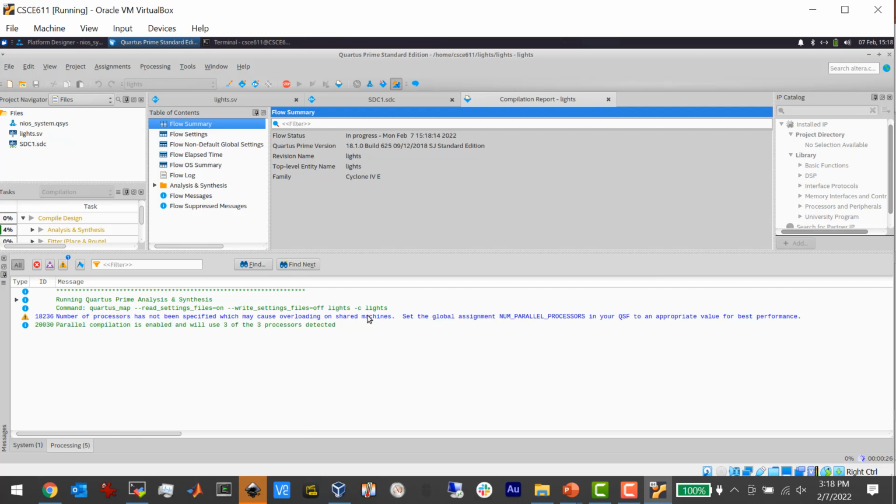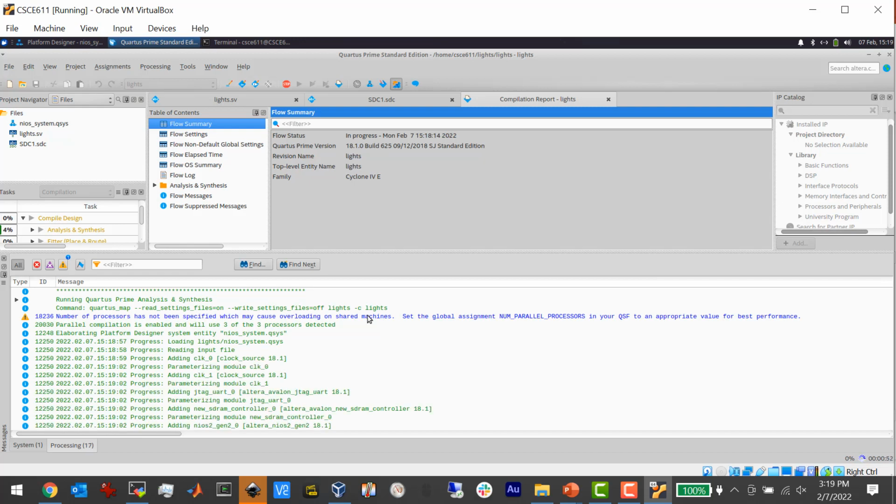The reason they call it a bitstream file is that it goes into the FPGA through JTAG, and even though I haven't covered it yet, it is actually a topic in this lecture, but I'll come back to JTAG here in a minute. JTAG is like SPI and UART and I2C in that it is a bit serial protocol. So all the bits that configure the FPGA go in one by one, and that's why they call this a bitstream file. That's also why it takes a really long time to configure the FPGA, as you will see once I get the SOF file to show you.